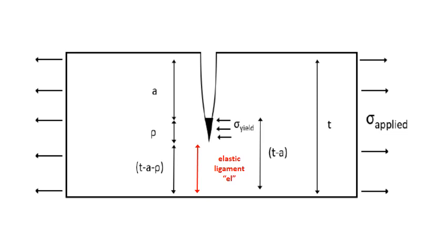If we have a lot of ductility at the crack tip, if we have a lot of yielding through that elastic ligament, we're going to blunt our crack, and we're going to be able to simulate a metal loss flaw or a corrosion flaw. And that's a very, very important thing. It's very important to think that our elastic ligament is going to get very, very small during a ductile failure or a plastic collapse type solution.